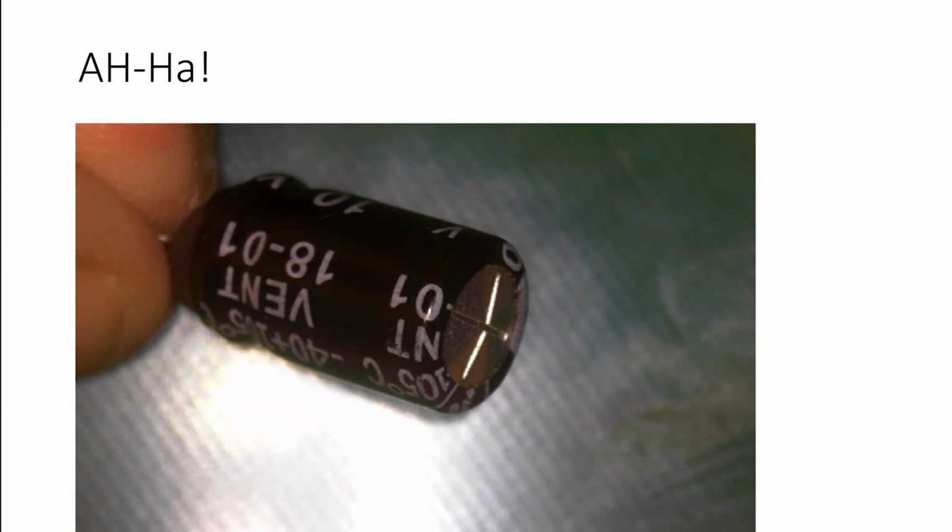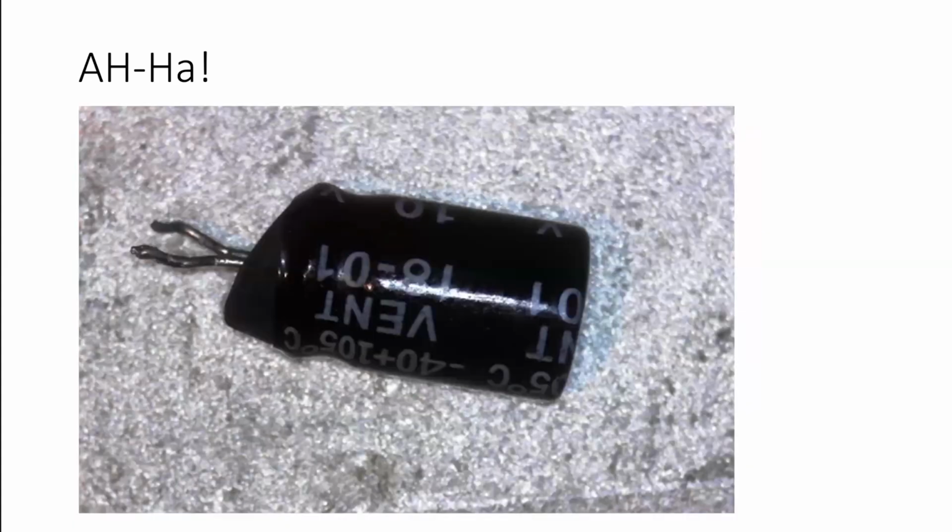Also, you can see down at where my fingers are, the rubber plug has come out, which is bad news. And notice the date code. The date code is 1801. Now that means week 18 of 2001. And that's going to be important because of a wee story that I'm about to tell you. If I take the capacitor and put it down, you can see that the base has also popped out. So this looks like a very sick capacitor.